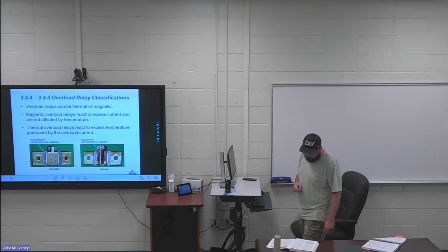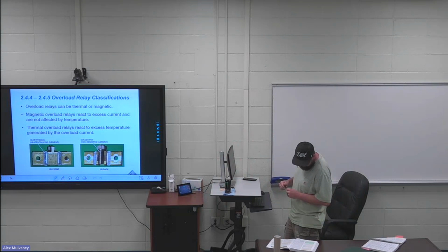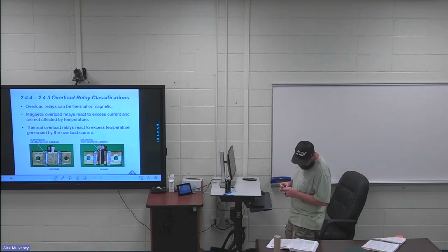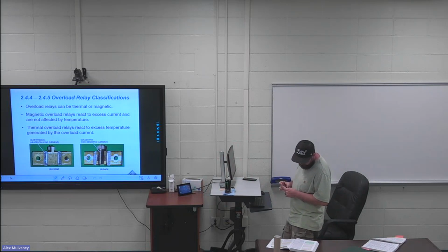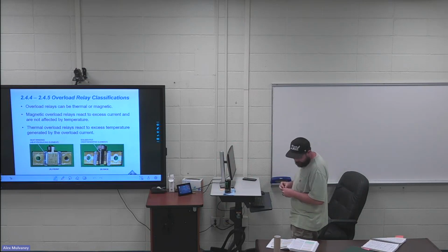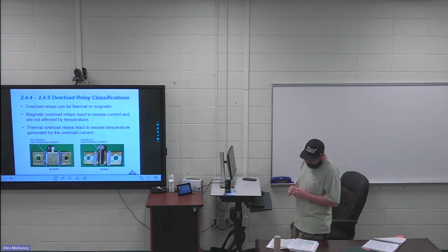Still talking about selection, moving on to page 17. That middle paragraph on the left-hand side of page 17, second and third sentence are highlighted. An alarm signal is sometimes required to indicate when a motor is stopped due to an overload trip. Also, in some machines, particularly those associated with continuous processing, you may be required to signal an overload condition rather than have the motor in the process stop automatically. So just know that these relays can be hooked up to alarms that let you know whenever stuff's tripped out or about to trip.